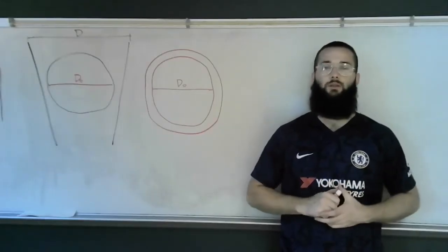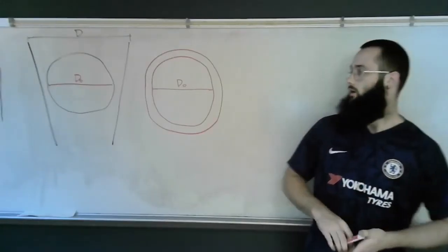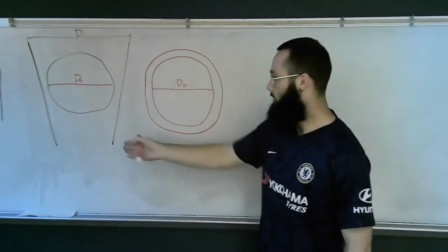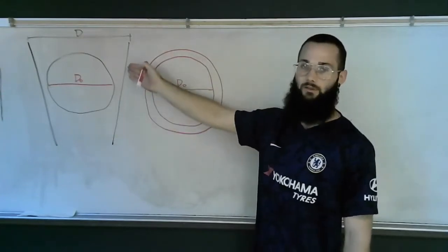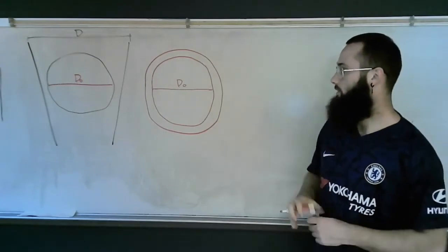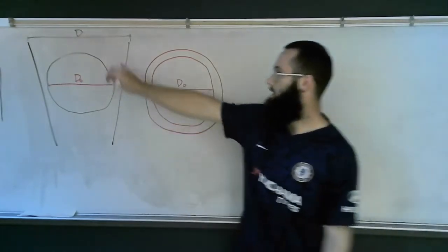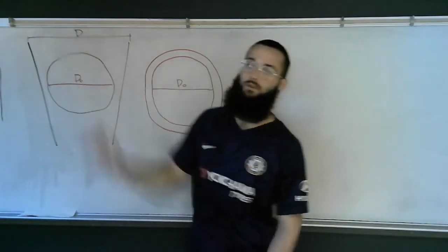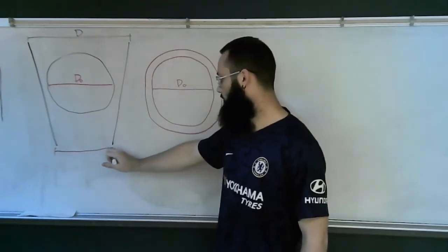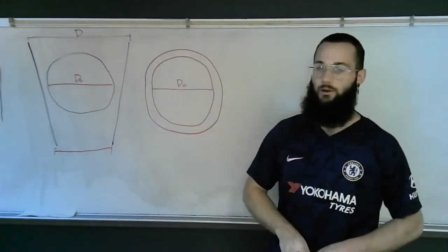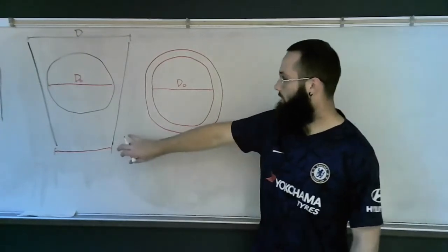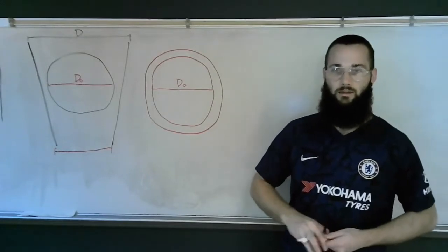Before we move on, I just want to take a minute to talk a little bit more about flow meters. In reality, the walls of this flow meter are not straight up and down. They have a little bit of a slope to them. Obviously, I've exaggerated it a little bit here, but that's just to make a point. The top of this will still have a maximum diameter of d, but the bottom will not have the same diameter because of the slope. So we want to use this slope in order to express diameter as a function of the height.